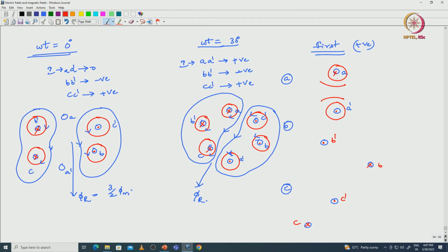For cross it is clockwise direction, for dot it is anti-clockwise. Then the resultant flux vector is in this direction for phi A. And with respect to the B phase coil, for cross it is anti-clockwise direction, the flux loops, and here it is in a clockwise manner for cross, for dot it is in an anti-clockwise direction.